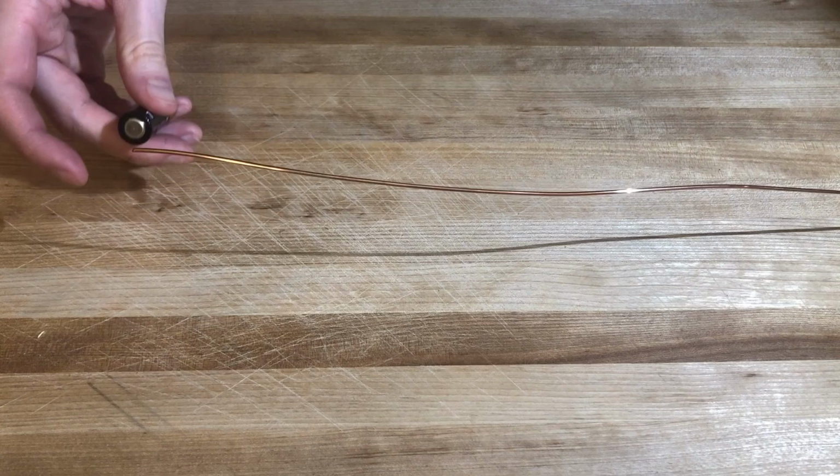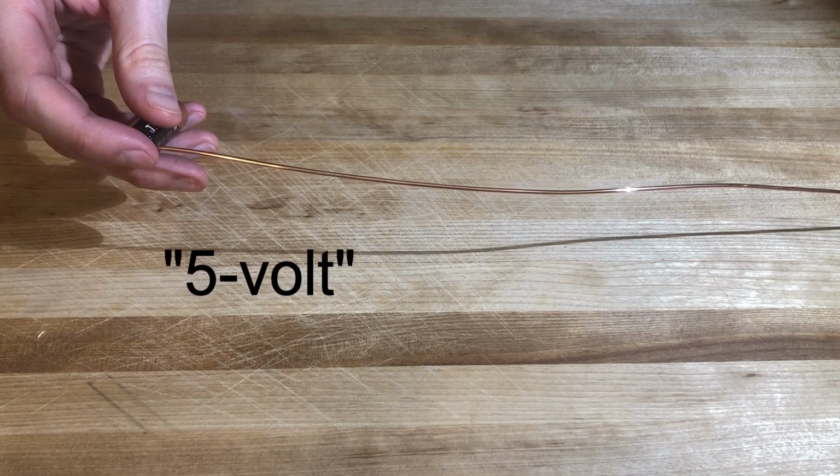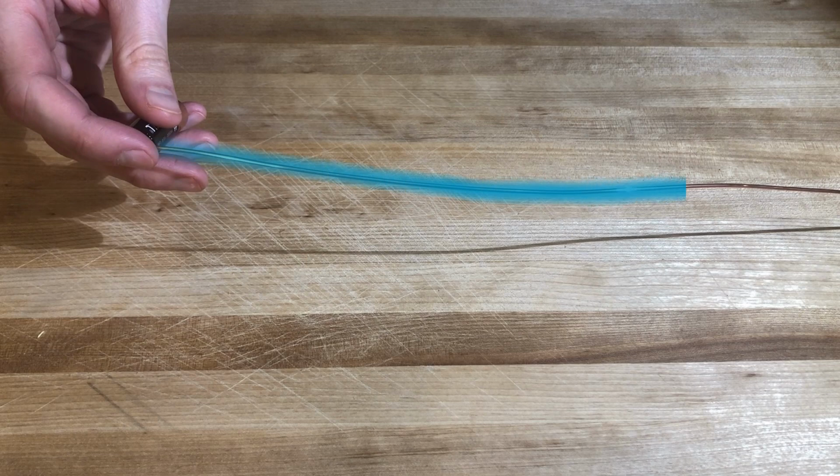Now that you understand voltage, we can explain what happens to a wire when it is hooked up to a power source. When I touch this wire to the negative side of a 5-volt battery, the surface of the wire will gain an electric potential of negative 5 volts. And since we have learned that electric potential is the result of electric fields, that must mean that excess electrons are flowing into the wire, giving it a negative electric charge.